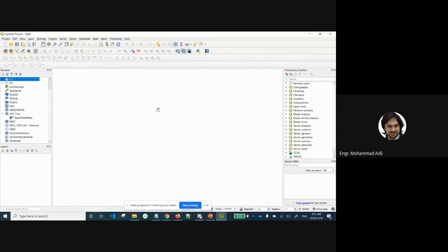In the bottom right here, it is showing EPSG 4326. So it is using the coordinate system WGS 84 already, and this is what we want to work in. This means it is already the planet Earth here, but nothing has been drawn yet.